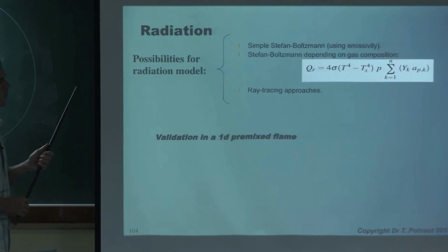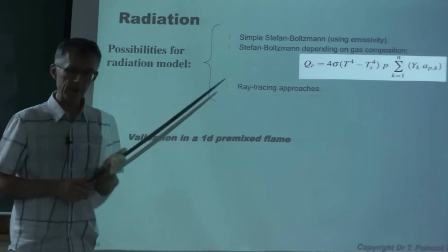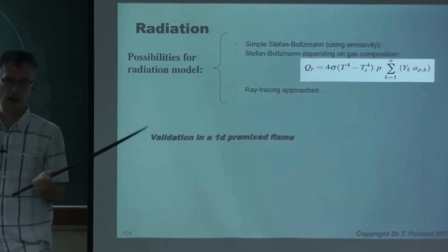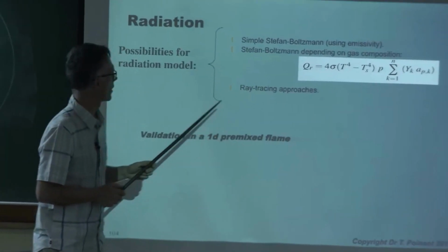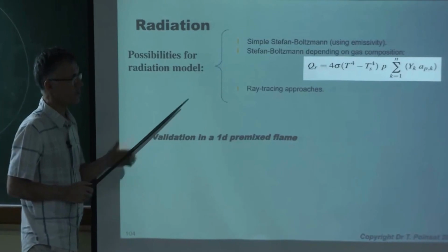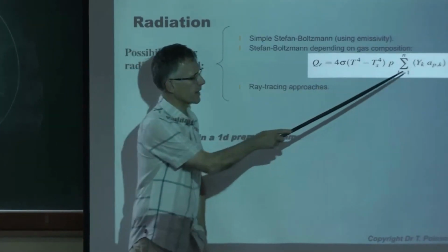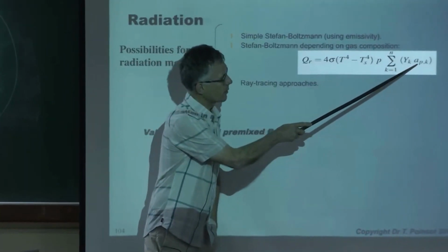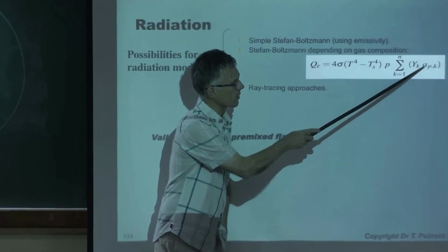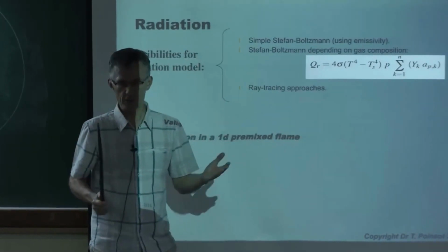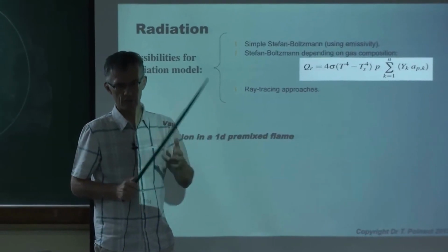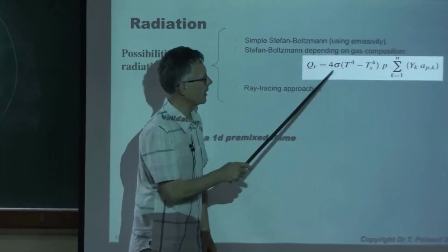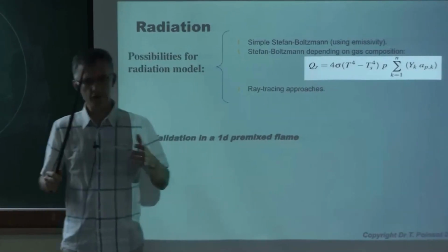Because we need to account now for this thing. We need to account also for radiation. So for radiation, you could spend your life working on that. There are good compromises here. One of them is this RADCAL program, where you just say that you have gray gases in your gas, and the emissivity here, the Planck coefficient, is given by the concentration of these gases, the mass fractions. So it's only CO2 and H2O, which radiate. So you plug them here, and that gives you an idea of the flux lost by radiation.